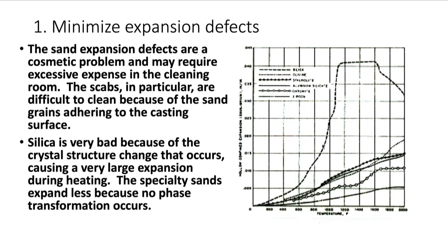And this cristobalite is the stuff that, when it breaks down, can hurt your lungs. There's something called silicosis, which is caused by long-term exposure to particles of silica sand, and it's usually the stuff that breaks down really fine. It's usually the cristobalite that is the bad actor.